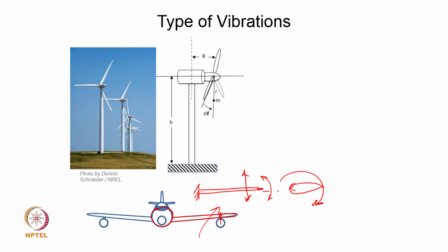So, if the wind blowing across this structure excites the twist, that means it can excite the torsion of this wing structure. In addition, you may notice very clearly that at the underside of this wing there is a turbine, is it not. So, that turbine is going to generate a thrust, that thrust will have its own moment around this beam cross section. So, if you are treating this as the structure, the forces will generate a twisting moment, and then apart from the bending vibration there would be a torsional vibration of this same wing. Okay. So, it is all up to us as to how and what we want to investigate, and maybe we should need to know all the different natural frequencies of a mechanical structure as we see here. Okay.